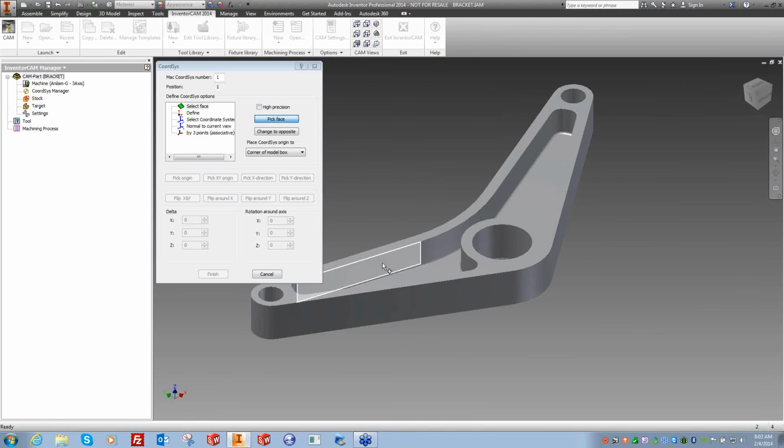You can reference it by 3 points, so if the part changes, that datum still stays the same even though the hole distance is changing. Or vice versa, you can actually have the associative point move closer to the hole but still be on that wall. Can be very powerful. Most people don't need that. It's really for special cases.